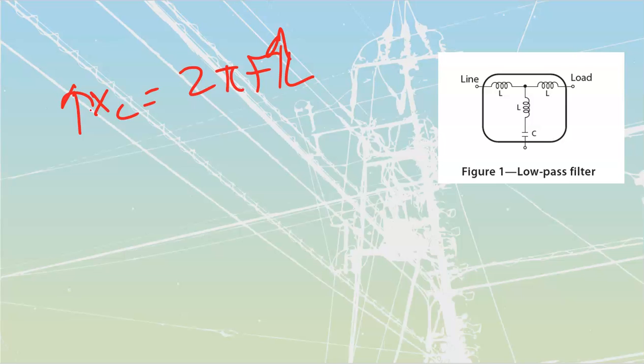There is one other type of transformer that has specialty windings that give flux cancellations. Basically, we're going to get rid of harmonics because we're able to push them against each other. We're going to use their own harmonic frequencies to counteract each other. Usually, we're going to have a zigzag connected secondary with a delta connected primary, and we are going to have a phase shift. We know about phase shift from transformers at the beginning of the year: we've got a standard 30-degree phase shift from A to neutral, as well as another 30 degrees anytime that we go from a Y to a delta or a delta to a Y, etc.